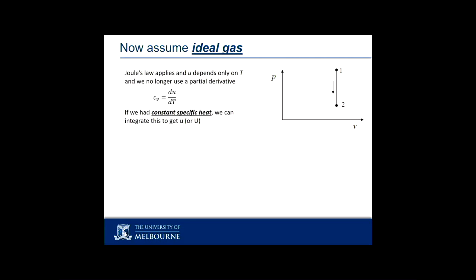If I had a constant specific heat, I could now connect internal energy to temperature through this equation, right? So I'd have U equals CV T, if I knew the CV, with a constant, which also means that if I'm doing a delta, the constant will disappear. Yeah? And that's the powerful thing. My delta U will be CV delta T, because the CV stays the same.